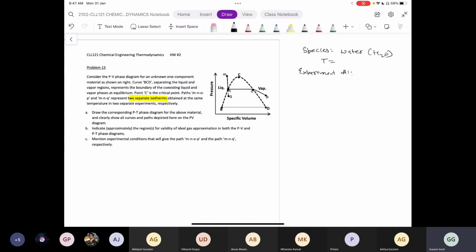Okay, and let us fix temperature also. Now you are, let's say, depressurizing water. In experiment number 1, the end state is a metastable liquid. So the videos I have shared, in those videos, pressure is constant, temperature is changing. The paper I have shared, in that paper, this depressurization is being done isothermally. So that paper represents better this particular experiment.